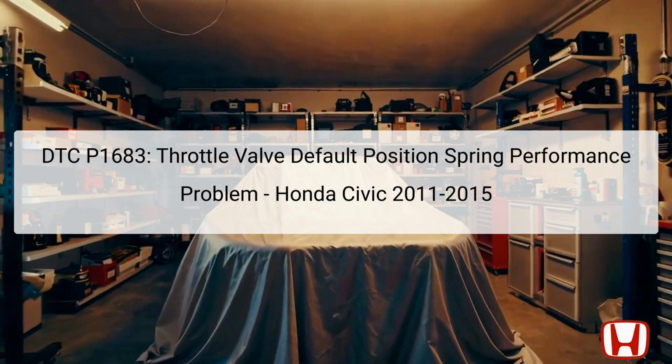The throttle valve is located in the throttle body, which is situated between the air intake manifold and the air filter. It is essential to address this issue promptly, as failure to do so can lead to reduced drivability and potential safety concerns. The implications of this error can range from diminished engine response to increased fuel consumption and even engine stalling, making it necessary to follow an accurate troubleshooting guide.